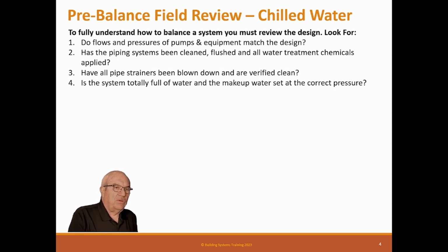Is the system totally full of water and makeup water set at the correct pressure? This is the Achilles heel of a water system. It must not have any air in the system. Plug flow or total bubble flow will affect your balance drastically. So you need to make sure it's full of water.